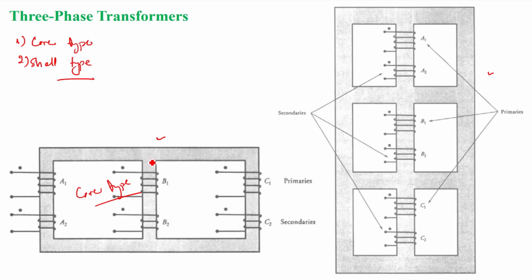There are certain advantages, because when we use three single-phase transformers, it occupies a lot of space, and also the volume and the cost become very high. Because we have three separate transformers, right? Separate insulation, separate winding arrangement, everything. So the cost increases and the space requirement increases.